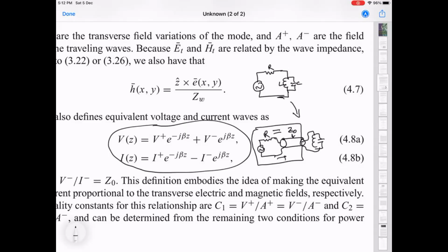interacts with this LC resonator, which of course is now an impedance mismatch, and then the wave comes back, and again there's no reflection here, and it goes back here. So there are no multiple reflections, and this is a very typical scenario, idealized somewhat, because there is no device where you have a perfect match. This R equal to Z naught is only a dream thing. You might have 50 ohms and 50.1 ohms, but it's still a mismatch. In reality, these numbers are actually much worse.